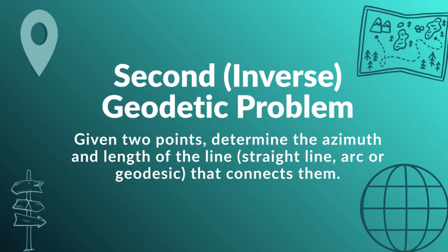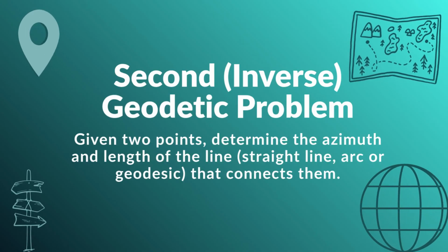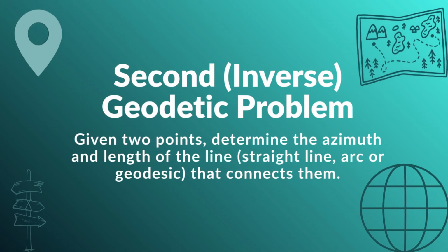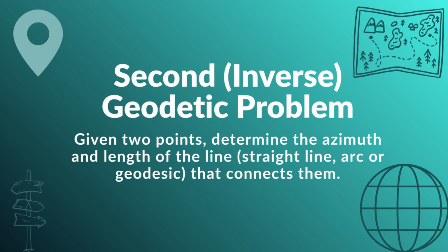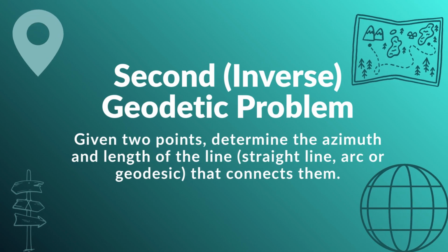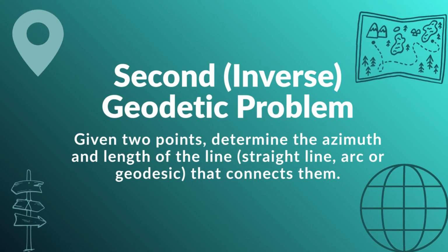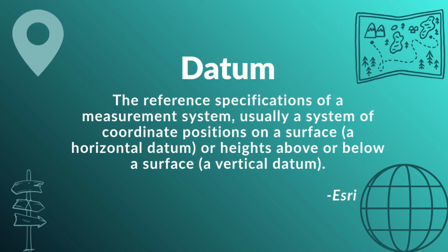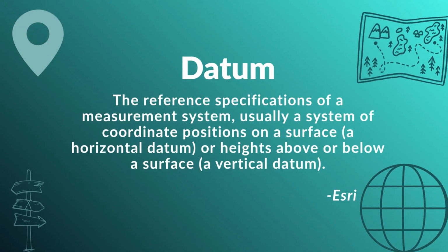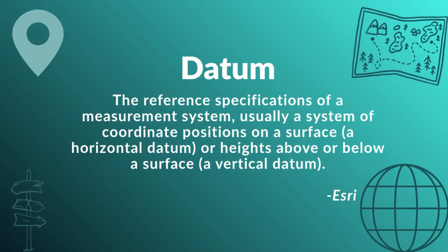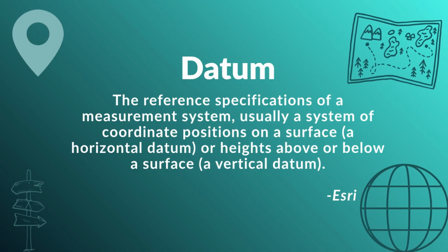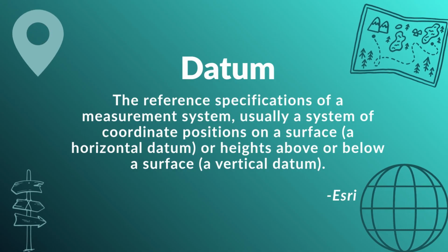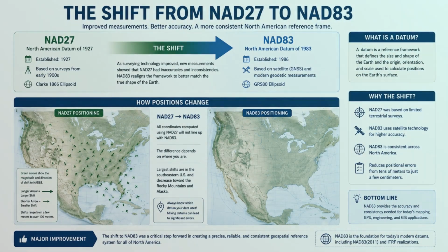Okay, so we have the shape of the Earth defined, we have the logic for calculating elevations, and we know how to measure distance across the curve. Right. But if I'm dropping a pin on a digital map, that coordinate system has to be physically anchored to the crust of the Earth somehow. And this is where we bring in datums. Datums. A datum is essentially the mathematical model that pins your coordinate system to the physical Earth. In geospatial technology, a datum provides your frame of reference. For the exam, there are specific horizontal datums you're expected to differentiate, starting with the two major North American ones.